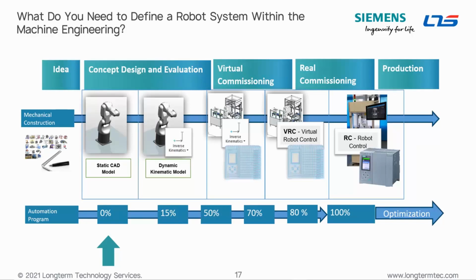I add my virtual PLC controller, for example, to start programming my first PLC code on that line. And at the end, I really bring the total PLC code over to the real machine, and I'm in a much better position to do the real commissioning right away from the virtual commissioning.